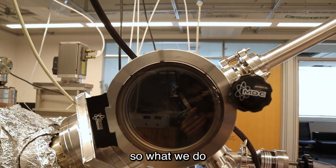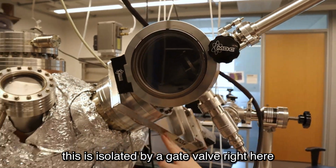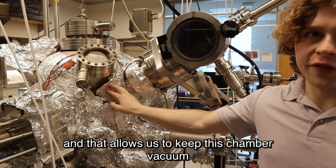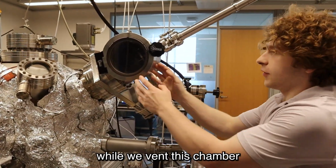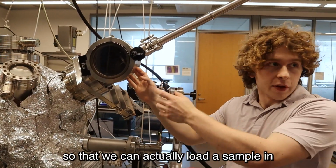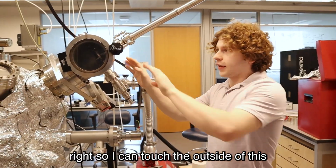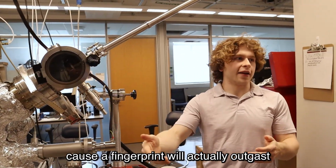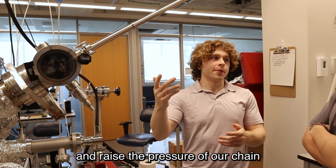And so what we do, this is isolated by a gate valve right here. And so we close this gate valve, and that allows us to keep this chamber at vacuum while we vent this chamber so that we can actually load a sample in, right? So I can touch the outside of this, that's fine, but I can't touch the inside because a fingerprint will actually outgas and raise the pressure of our chamber.